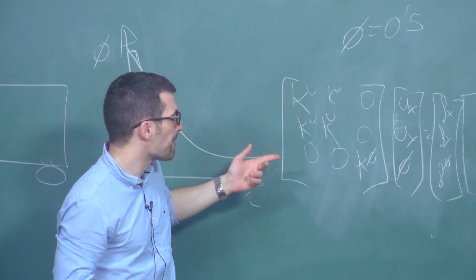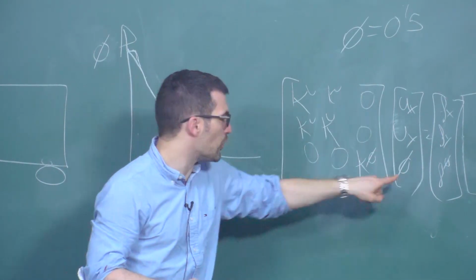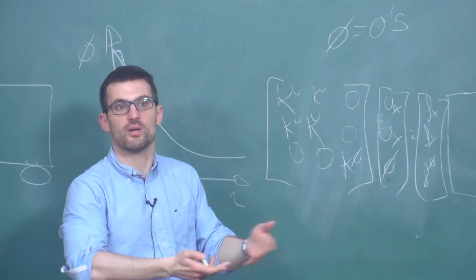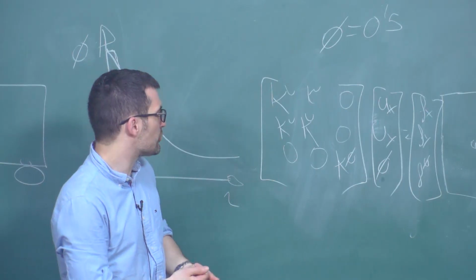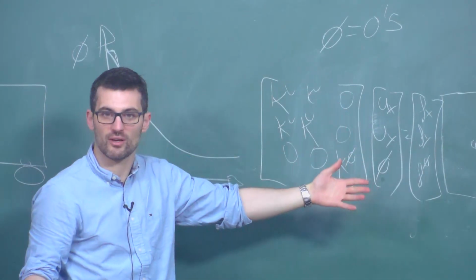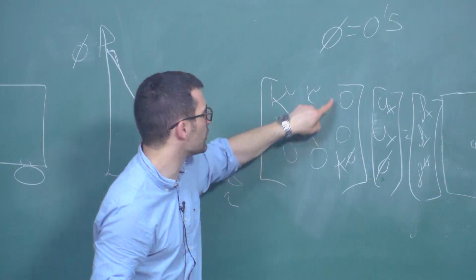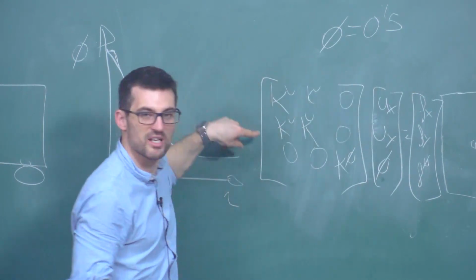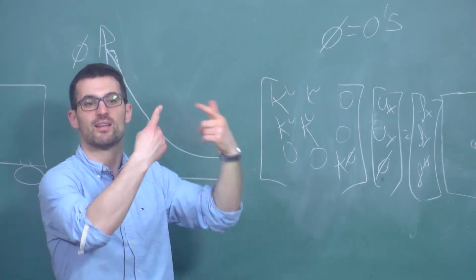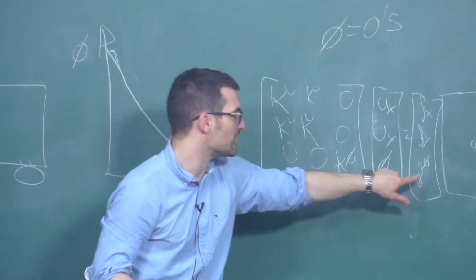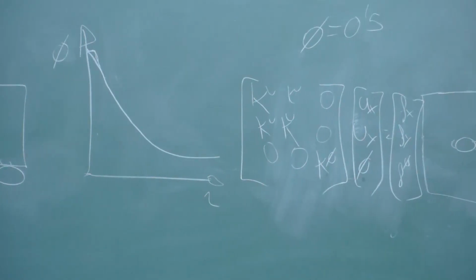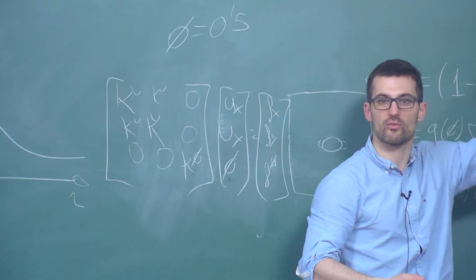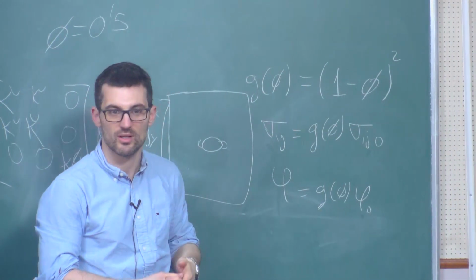Because we said, okay, we need to implement things. We need to add an extra degree of freedom. So for sure, we need to define our own user element, and this is the way we implemented these things first. So we basically come up with a Fortran code where we reproduce first the Abaqus elements and displacements, and then we said, okay, now we add an extra term that will be that stiffness matrix and residual associated with the phase field. So we took the phase field equation, we applied a weak form, and then we derived the residuals and stiffness matrices. That was the idea.